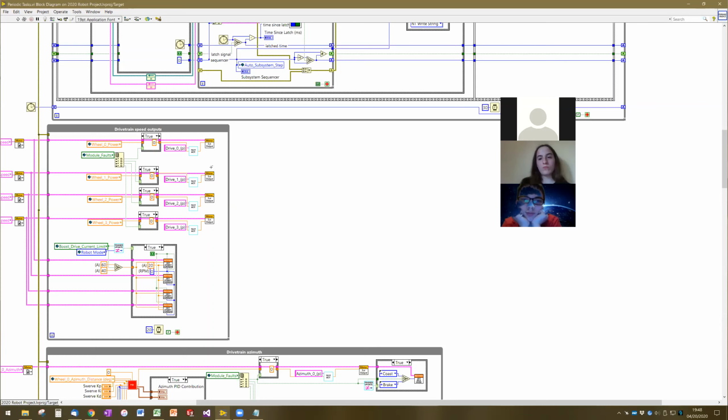And that is not strictly true. And so as the battery changes, the behavior of the merging between the robot's rotation and the robot's translation will behave differently. The even better solution is that instead of applying a certain amount of power, you apply a target speed and have a PID and a feed-forward controller that maintains the wheel velocity, so that you're setting a goal velocity, because what we'll find is that the math that we're going to work out today or next lecture is not really giving a goal power.